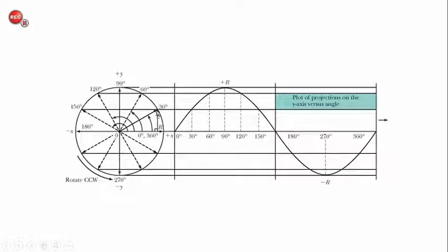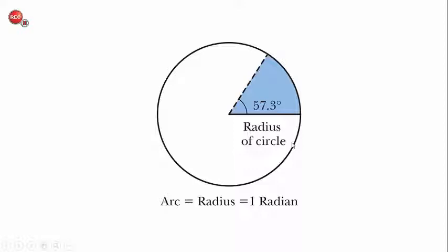And if this conductor continued to rotate, it would eventually be moving left to right through the flux field, and therefore the direction of current flow will have reversed, and that will be the negative alternation of that sine wave.